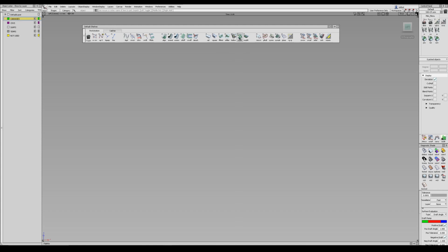Tubular offset for offsetting either curve on surfaces or trim edges, and then draft, model place surface draft. And these are my core surfacing tools. That's basically all I use for most of my projects, regardless if it's concept or for production. Trim convert allows you to take a four-sided trim patch and convert it to a natural boundary surface, which is awesome for really controlling or technical surfacing, Class A modeling parts. Planarize hull allows you to move all your hulls into a plane or a straight line, both symmetrical modeling and symmetry plane align. And then my construction plane and toggling.